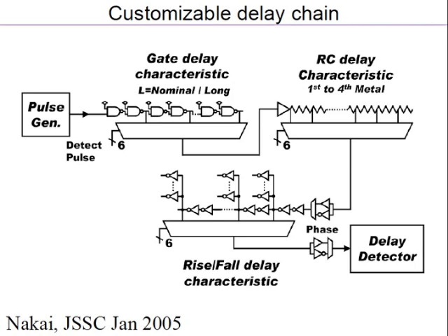If you say, look, I'll adjust the voltage so that from input to output this is 1 nanosecond, and that voltage ensures that this is 1 nanosecond, then with high confidence I should be able to say that the same voltage, if I apply it to the actual chip, will also run at 1 gigahertz. That is the intent here. So there is no reason to be measuring these individual groups, because the whole chain as a group is supposed to model the delay of the critical path.